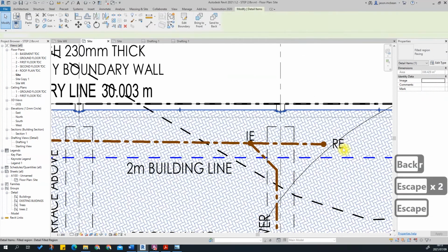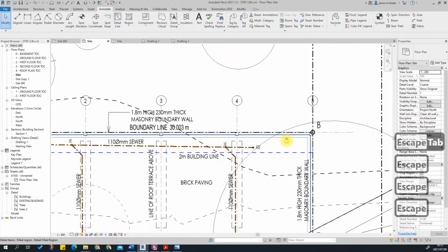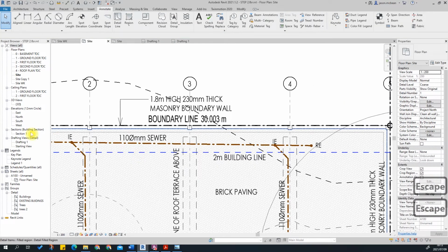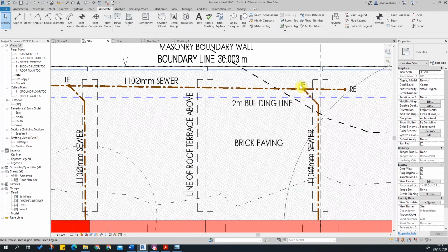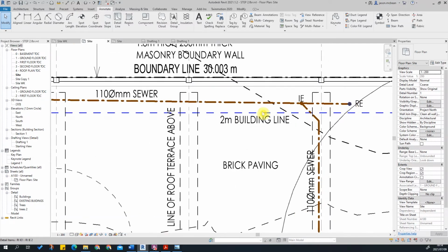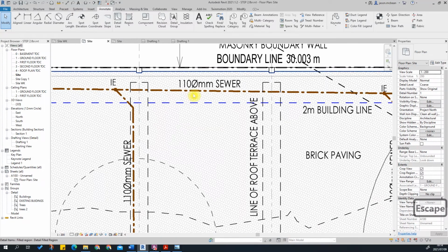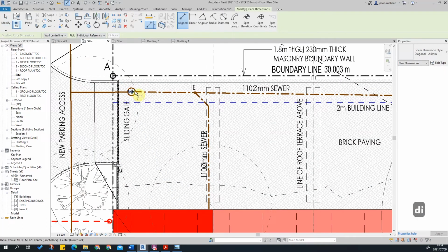It's either called a cleaning eye or rodding eye. It's just so that here they'll put a rod in to go and clean. There'll be some inside the basement as well where you can rod to this point over here. So all that you're trying to do is you just need an access point where you can rod. There might be another one over here. So every 15 meters, but I think this should be good if I measure.